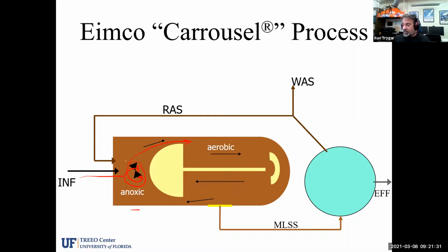So the flow comes in and pushes itself through this little gate or channel right here. So we have denitrification occurring here. So we have our nitrogen gas coming off here, and then we go into this basin for the ammonia to nitrite to nitrate processing, and that's occurring here. So we end up down at this end with some nitrate.